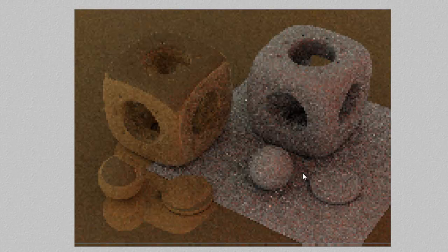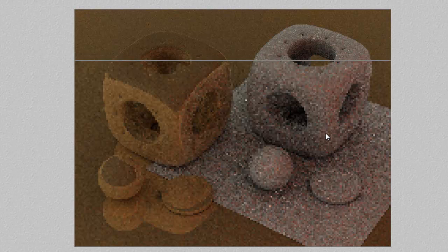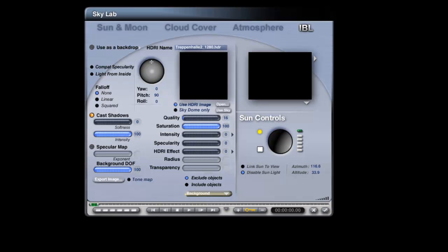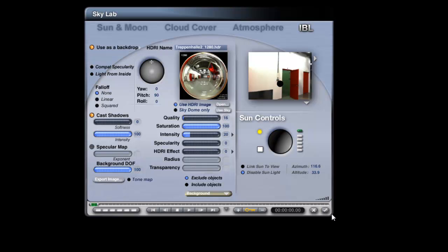There you go. And now you can see we've got quite a strong influence from the colour from the backdrop. So remember, previously with the boost light we were still getting some red on this side, but there was so much noise it was interfering with the effect. Now we're just getting quite an even lighting, and we're still getting the colour, which was the most important aspect of this. Now I can consider putting the backdrop back in, and at this point use backdrop, and as you know it's added to sky, and I was going to go for the intensity of 20. So now I've got backdrop to drive the reflection component.